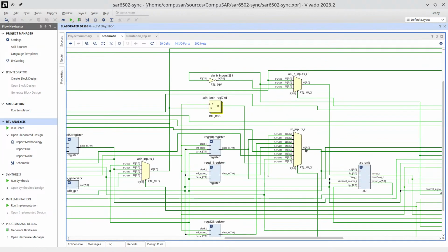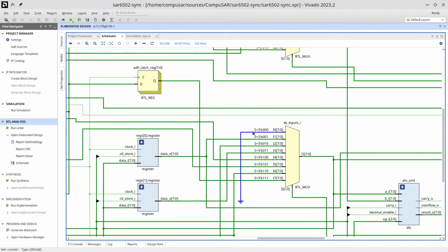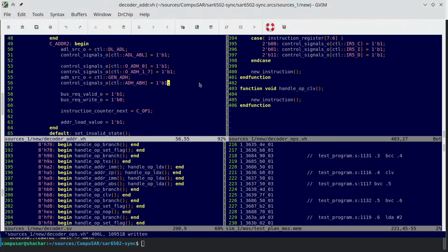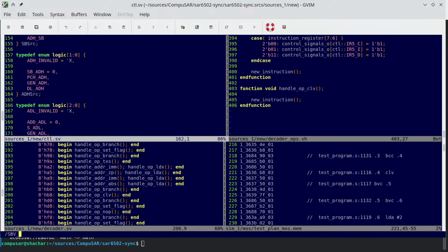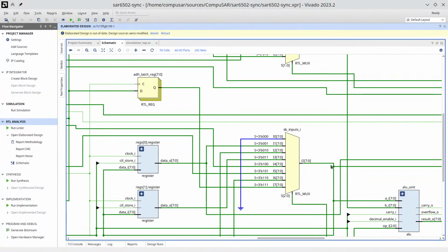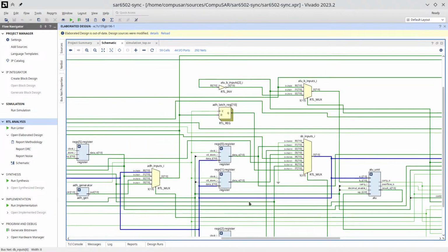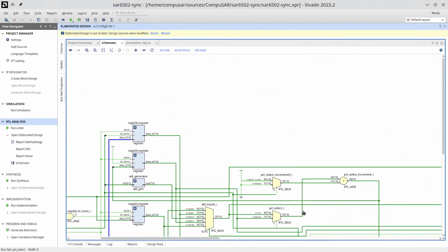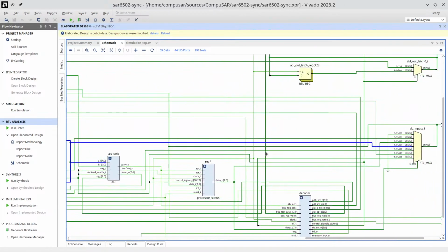Everybody can read it like this, right? SB inputs, and you see that we do have an input that is all zeros. So I can set the special bus to all zeros, which I can do with, it's not like I remember, right? SBSRC, OSB, obviously. So SB source is CTL OSB. And then another thing I can do is the special bus can actually feed the data bus.